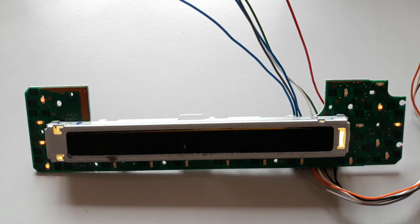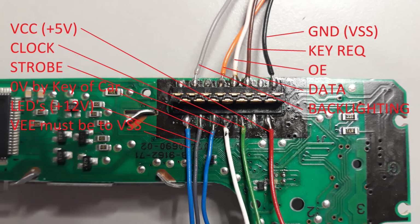As is common with many car radio displays, there are separate power supplies for the logic circuitry and for the backlight and LED illumination. On this panel, there are 2 dedicated power inputs for that purpose. You can think of them as the dashboard illumination and the radio illumination when the unit is switched on. With these details in hand, it becomes quite straightforward to bring virtually any display based on the uPD16431 driver back to life.